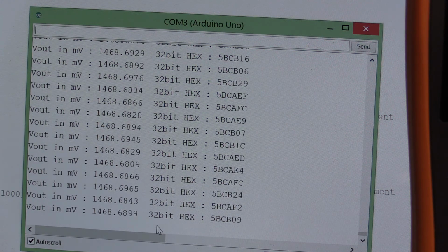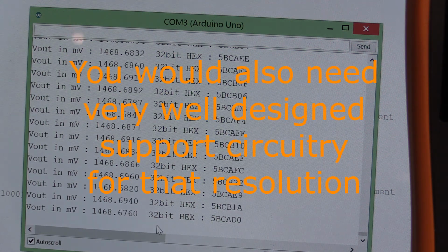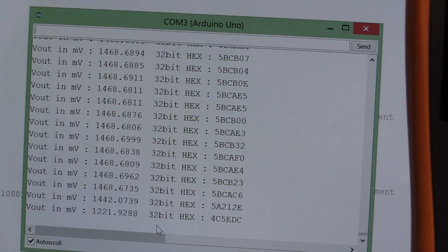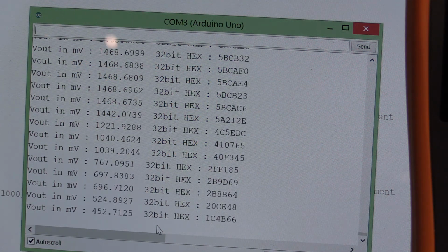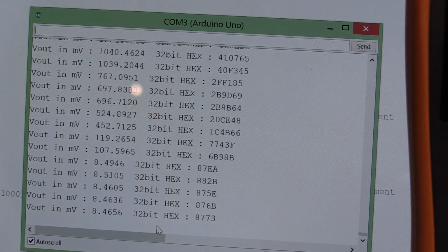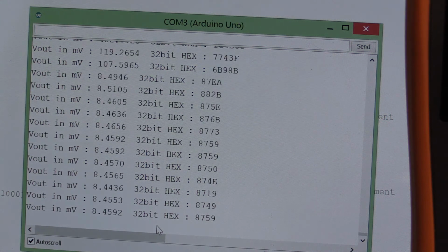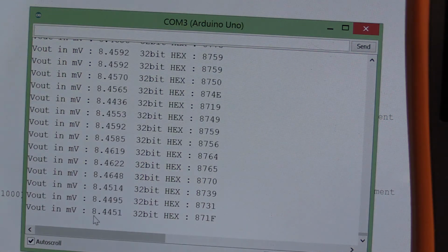The rest is there if you ever wanted it, but what I would say is that if you were going down to that level, then you would start leveraging the programmable gain amplifier and automatically adjust it so that you're amplifying the signal up rather than trying to work in the low end of the A to D converter. So I've just cranked that back down to 8 millivolts.